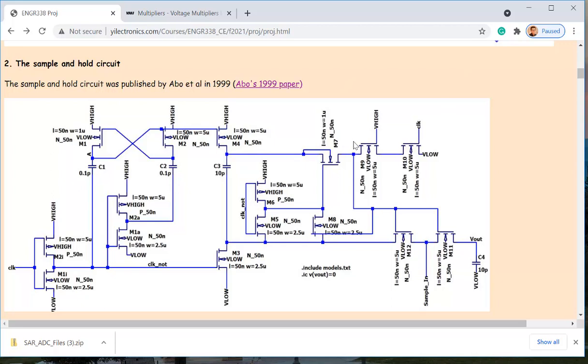So what this circuit does, it has a floating VDD over here, and then what's going to happen is here is a sample in, which is a V in, a sine wave voltage in, and this transistor will be on. Don't worry about why it's on, but it's on. So this V in will be added to here. Remember, it's still the same concept. You already have a VDD across the cap, but this voltage in is trying to dump more charges to here.